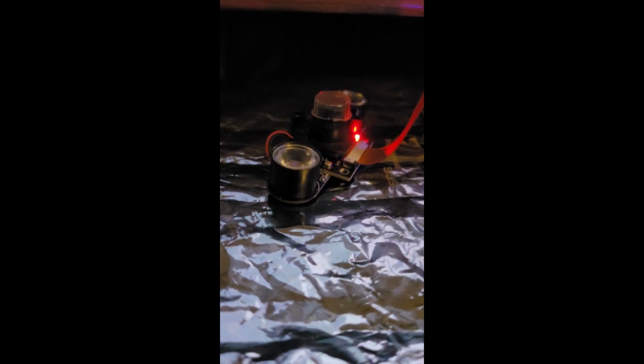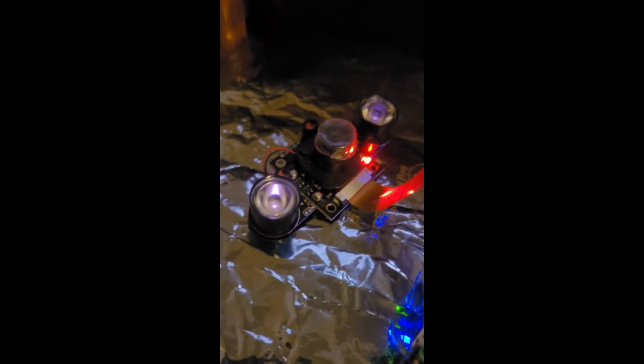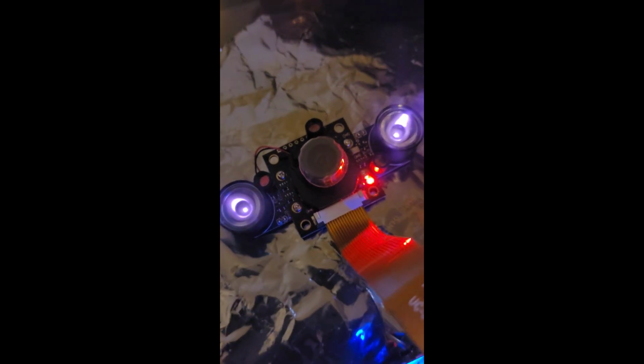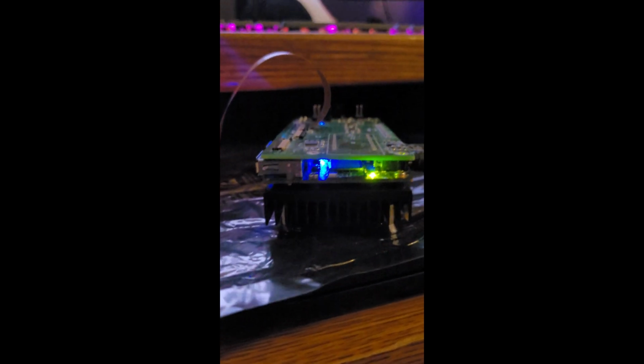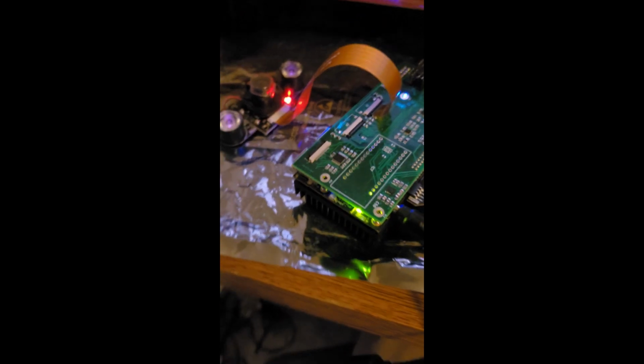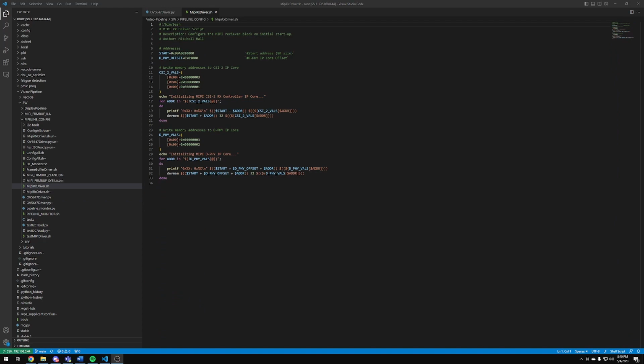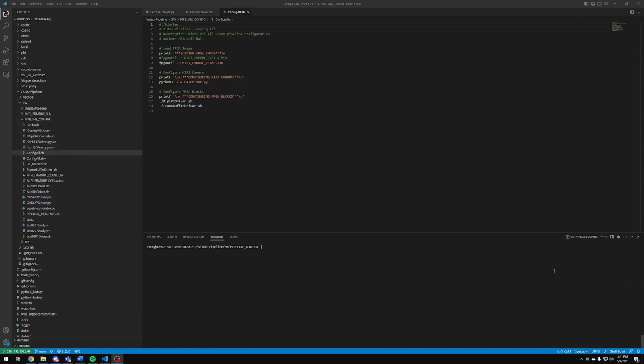To capture video data, we need an image sensor. Luckily, you can buy one, and previous teams have designed a board that connects the chosen image sensor to the rest of the Ultra 96. But the image sensor needs to know what to transmit, and the Ultra 96 needs to know what it's receiving. To do this, they both need to be initialized by driver scripts. We chose to write the image sensor driver in Python, where we can change the resolution and frame rate with these different groups of values seen here. And we chose to write the receiver driver in Bash. The image sensor and receiver were monitored by yet more scripts to make sure the data was moving through the system correctly.